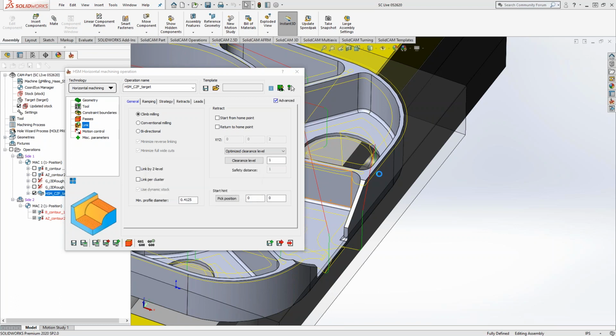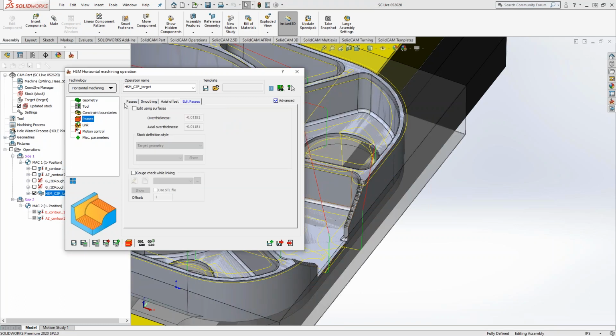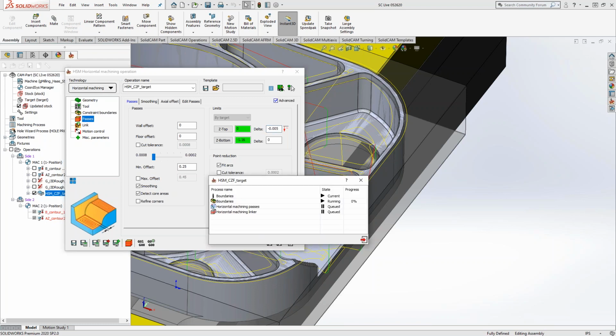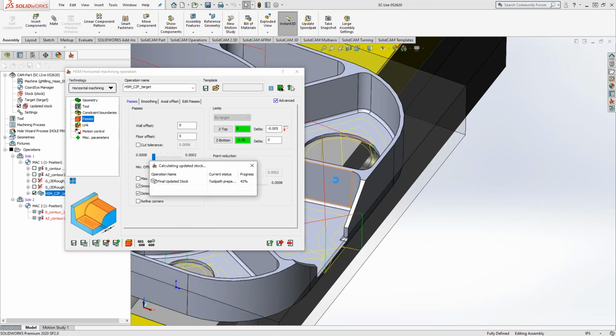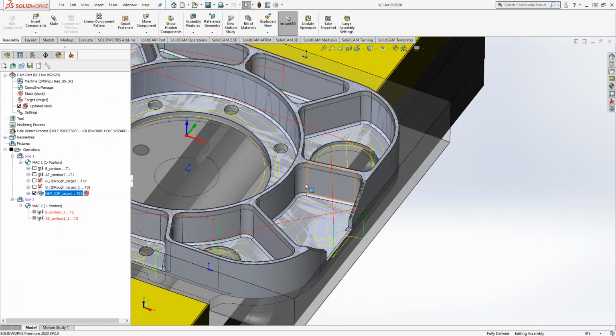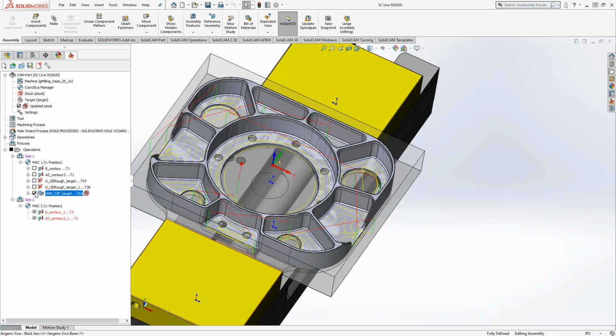Yeah, and that's where the benefit of those deltas comes in handy for you guys. You can set the Z top as the top of the part, but if Mark puts like a minus something real small in there, it will completely avoid that top surface. There you go. So now you can see that it avoided the top surface, and the toolpath is just doing the horizontal areas. So all my flat bottoms have been done by the part.